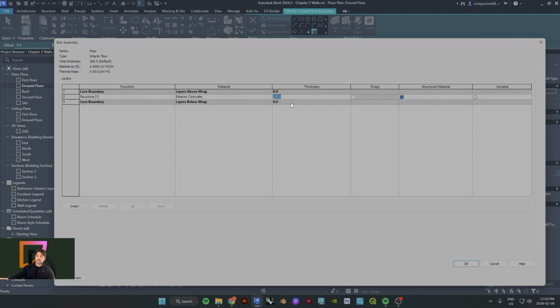Edit the structure just as you would with your walls. So now you're starting to see a pattern here of how these things function. Almost everything in Revit operates with the same kind of approach. You're duplicating families, you're changing the parameters, and you're using those new parameters to do what you need to do. So I think that value was, what did I say, 472, maybe?